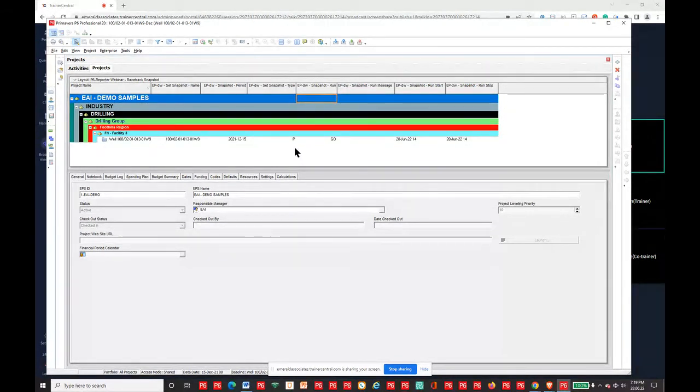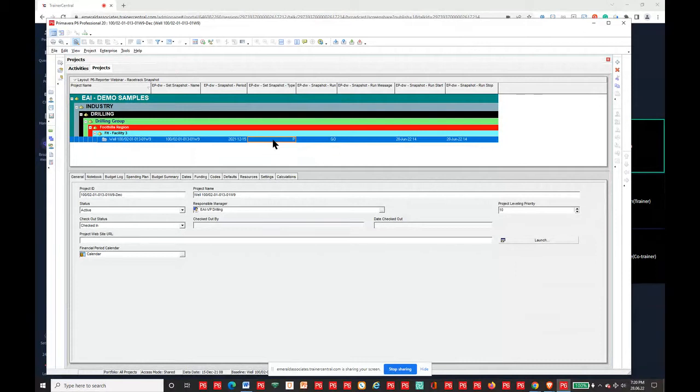Realistically, even in a turnaround situation, you could be taking them after each update, because very commonly on turnarounds that I've worked on, we have put a lot of labor into creating the comparison reports that Nicole was speaking about. So if you took your snapshot after each update, it's easy. You've got the information there. You can have the report pre-formatted, and you need to feed the snapshots into the report. Your work is done. Very easy.